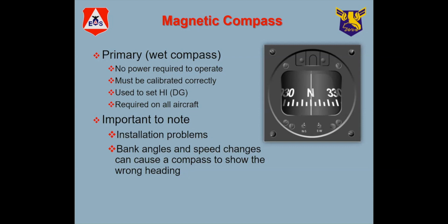And it's important because runways are numbered based on the magnetic heading of the runway. So if you're going to land on runway 36, that means you're going to be facing north, or 360 degrees. If you were told to take off from runway 270 and your magnetic heading when you're about to sit on the runway is something other than 270, you have a problem. So you need to set the directional gyro, and the compass should match what the runway heading is.